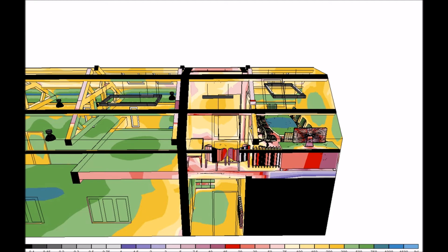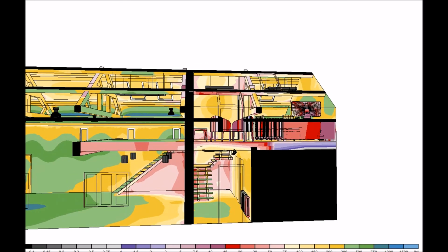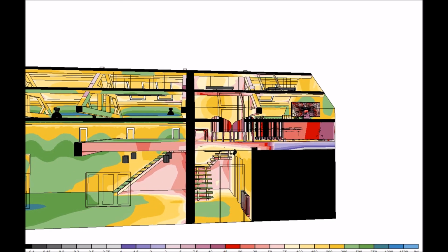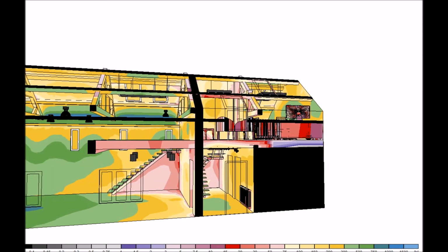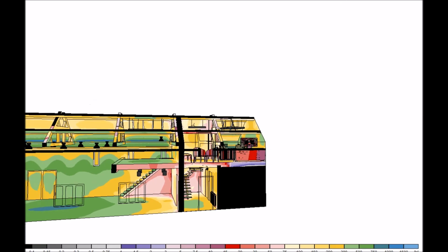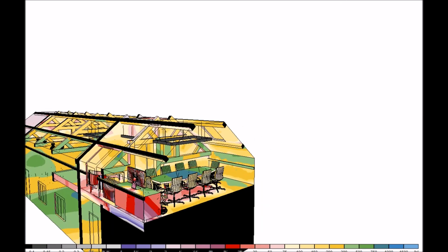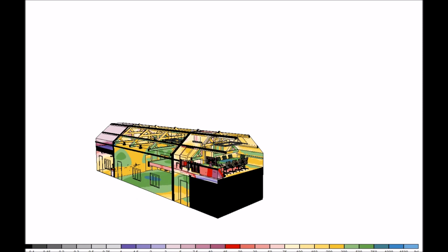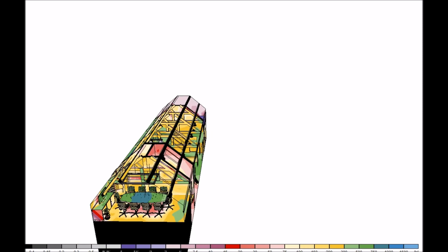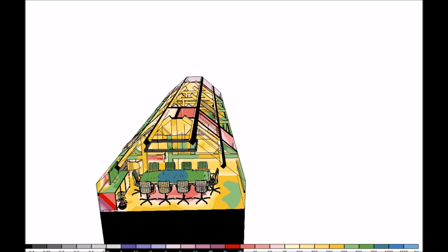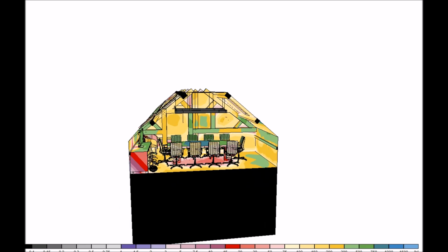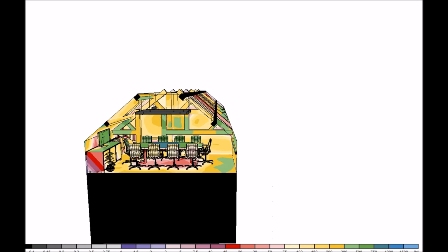And on the walls, you can see where I put the spotlights, so we can make something of wall displays or pictures just to make the entrance look a bit nicer. I've only got them focused on that one wall, but obviously they can be pointed wherever. And then round to the meeting room here, you can see this is again the same kind of lux levels, between 500 and 750 lux for that, which is what we want for a meeting. Again, glare's all compliant, and we've got a good level of light on the walls and the ceilings, you'll see.